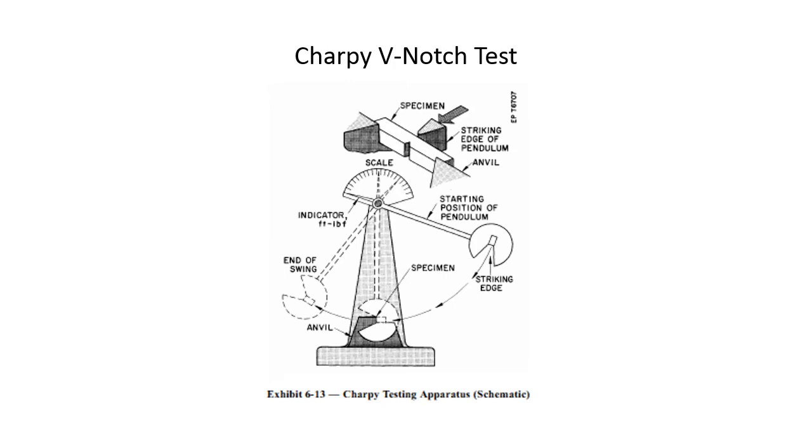And you do this on multiple test specimens, not just one, because I keep preaching this, but the data that you receive from just one test specimen, there's a good chance that it's out of the ballpark. So if you based your decisions on one test specimen, you wouldn't be getting a good answer. You might be, but there's a reason why they do these things in multiples of 3 or more.